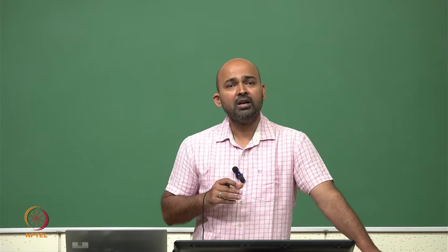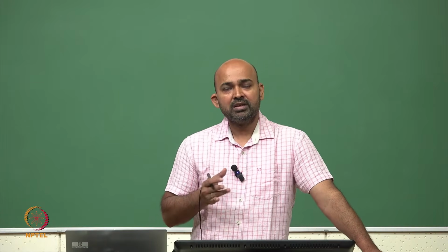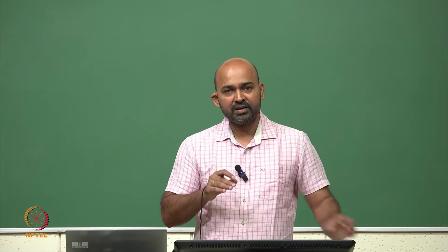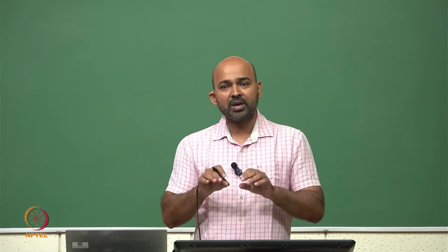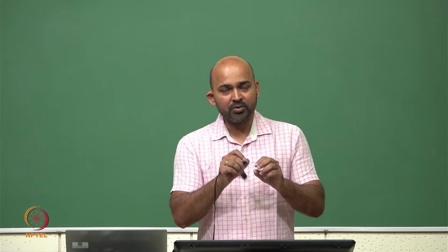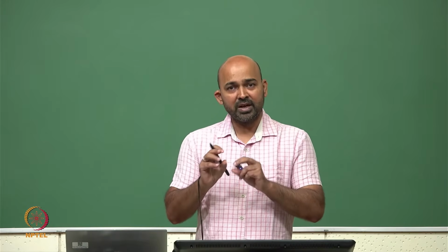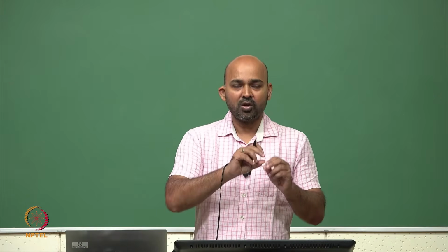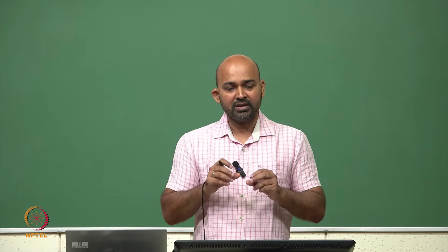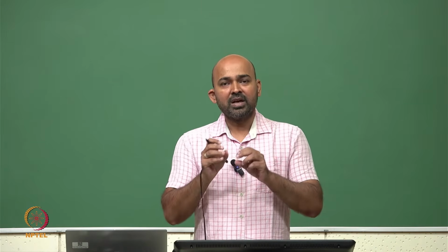Now, there are statements in SPICE where we can tell SPICE or LTspice that I am going to use a third party model. There is a proper statement or SPICE directive for that, called .model or .subckt, that is, subcircuit. These are the SPICE directives.